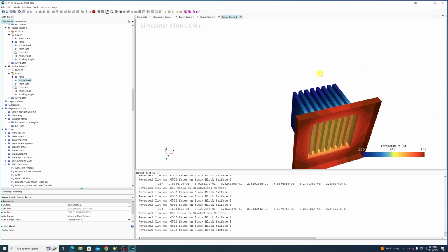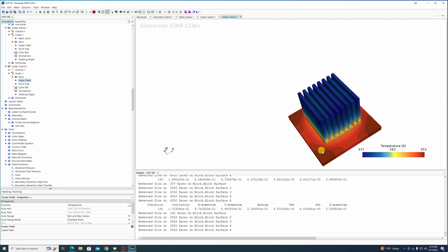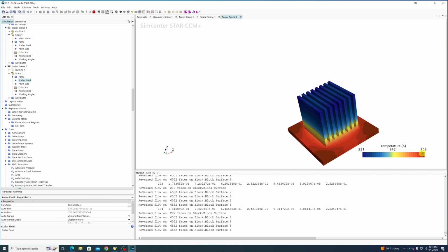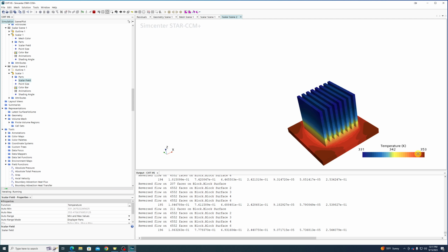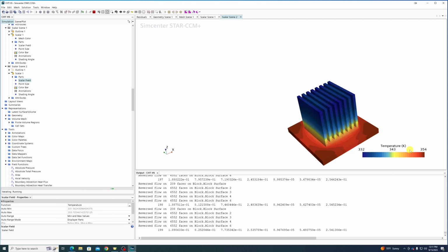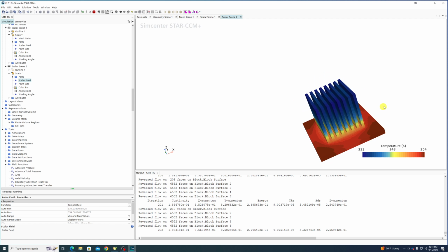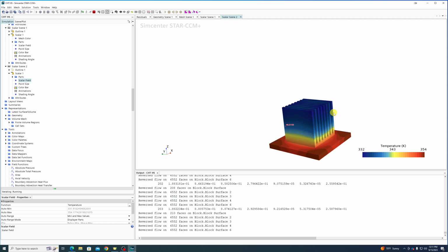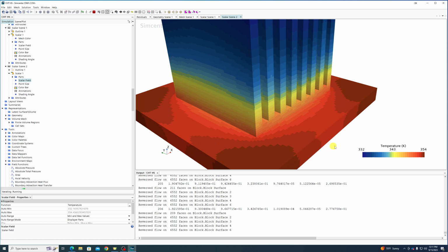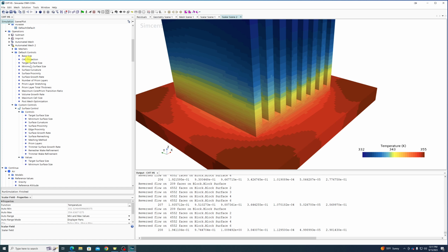So theoretically, if this were fully converged, which it's not, we would say that probably the bulk temperature of this chip gets to something like 348 Kelvin, somewhere in that neighborhood. So it gets to about 75 C, give or take. Maybe that's good, maybe that's not, but if this were a hypothetical actual engineering problem, that would be the current outcome, assuming this were fully converged. Again, it's not. It is very, very not fully converged.